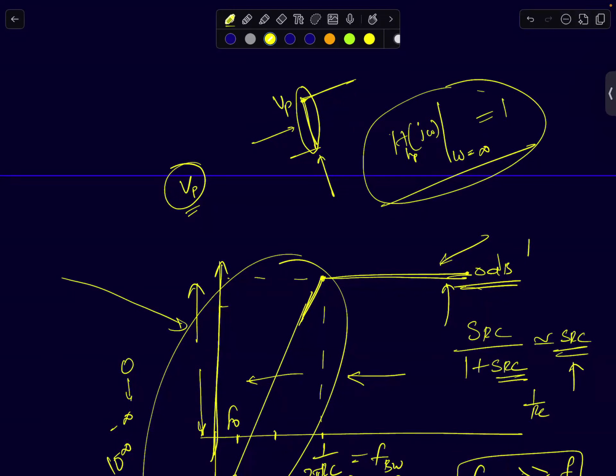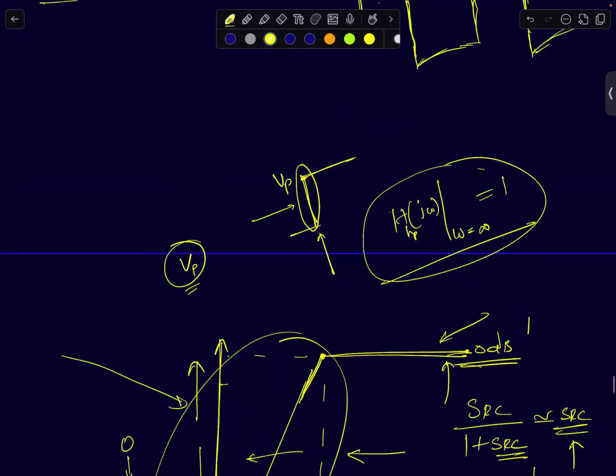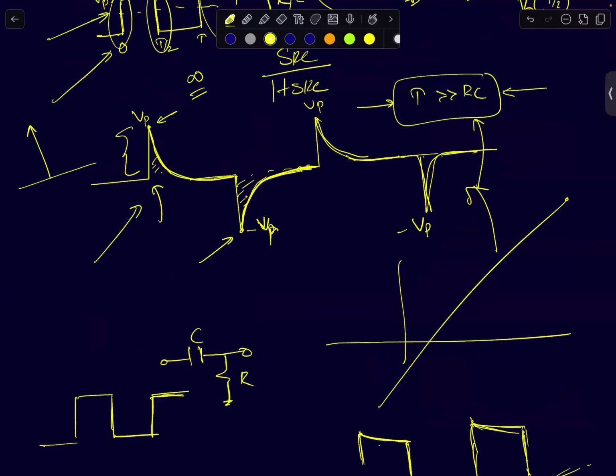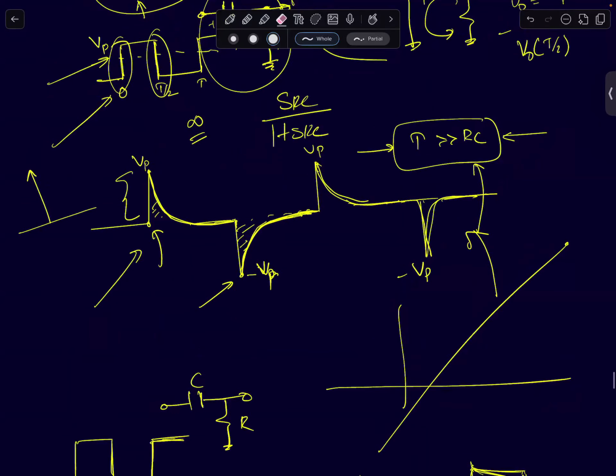That's a frequency domain interpretation, which is why here you see it's 1 Vp in the positive half cycle. When it goes from 0 to Vp, it's the positive half cycle, and the maximum step jump is 1 Vp, 0 to Vp volts. On the falling edge, the signal goes from Vp to 0. So that's a delta change of minus Vp, the net negative change, and that's the same as the output signal's peak. So why are we getting minus Vp and plus Vp?